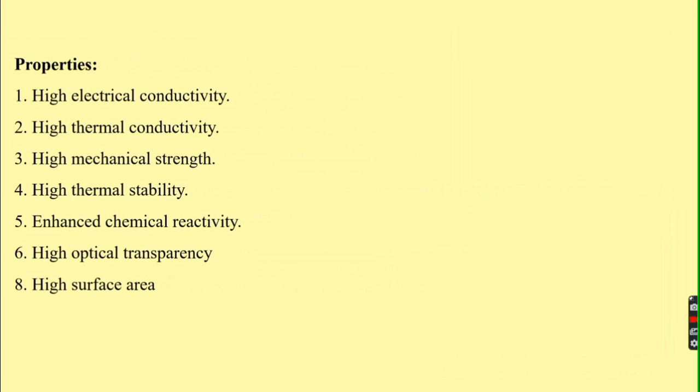Then we'll go to the properties of CNT. Almost all CNT have highly electrical conductivity, and they are very strong, 20 times stronger than and 6 times lighter than steel, hard as diamond, and the thermal capacity is twice that of pure diamond, with distinct anisotropic thermal behavior along the axis having a high thermal conductivity.